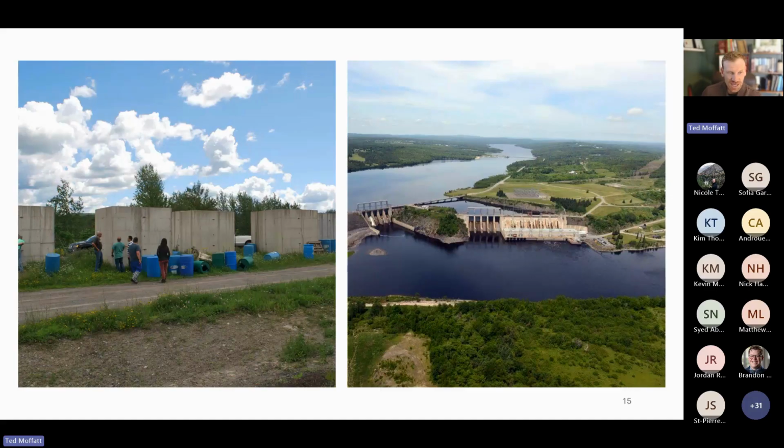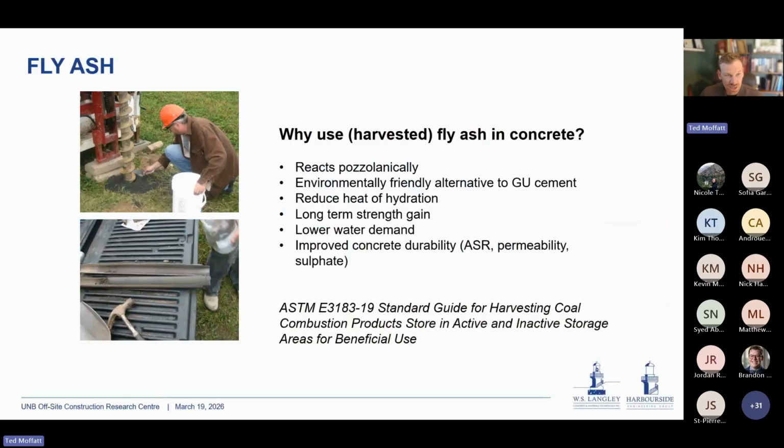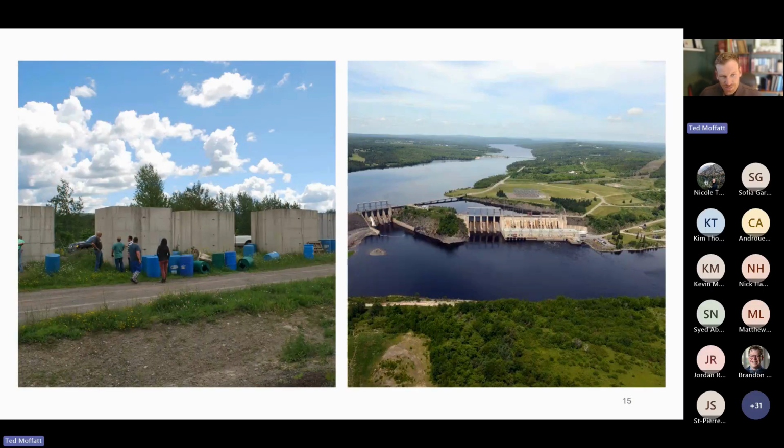So in this case, they looked at what effect using the same reactive aggregate that was used to construct the dam would have in the event of 30, 40, 50% processed ash, but also this block that's off in the distance, 50% reclaimed ash. This would have been ash that Mike is seen scooping here into this bucket. So it would have been used. And these blocks are some of the biggest research blocks in the world. I believe they're 10 by 10 by 10 feet.